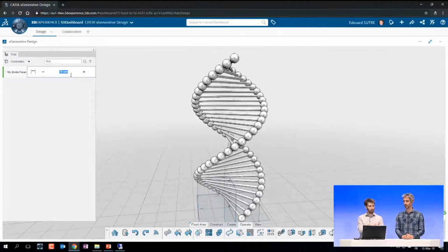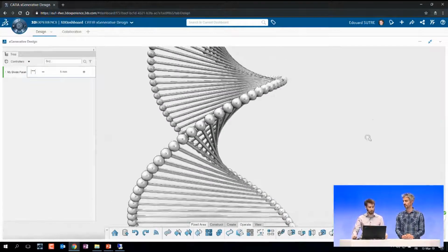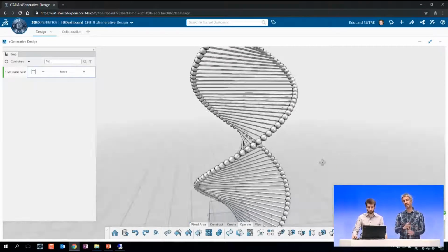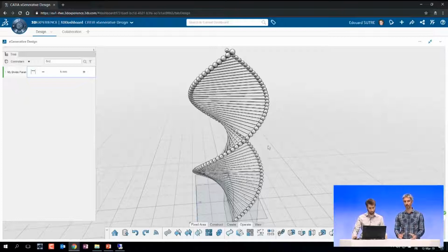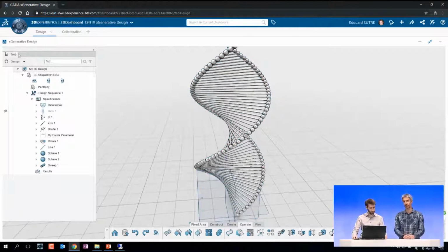And this is a simplified view to just expose your favorite parameters. And with that, you can play with your model. For example, if I change this value by 5 millimeters, it will increase a lot and it will update all my model to explore different alternatives. And you see, I'm generating a lot of objects. So here you just hide all the complexity of the design creation. You just expose one parameter which is important, and you make it available to anyone who wants to play with your model.